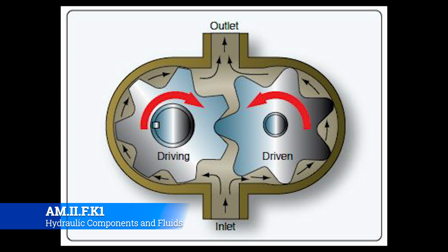Now, keep in mind, with a lot of these different types of hydraulic pumps we're going to get into, at the end of the day, as the mechanic, you're just going to remove and replace them whenever they go bad. Where this is going to help you is with troubleshooting. Say I see that the hydraulic pressure is just not what it should be. Let's say it's supposed to be at 1,000 psi and it's at 950, and I just cannot figure out why. And last week it was at 975. But the pump is still good as long as it's producing 900.